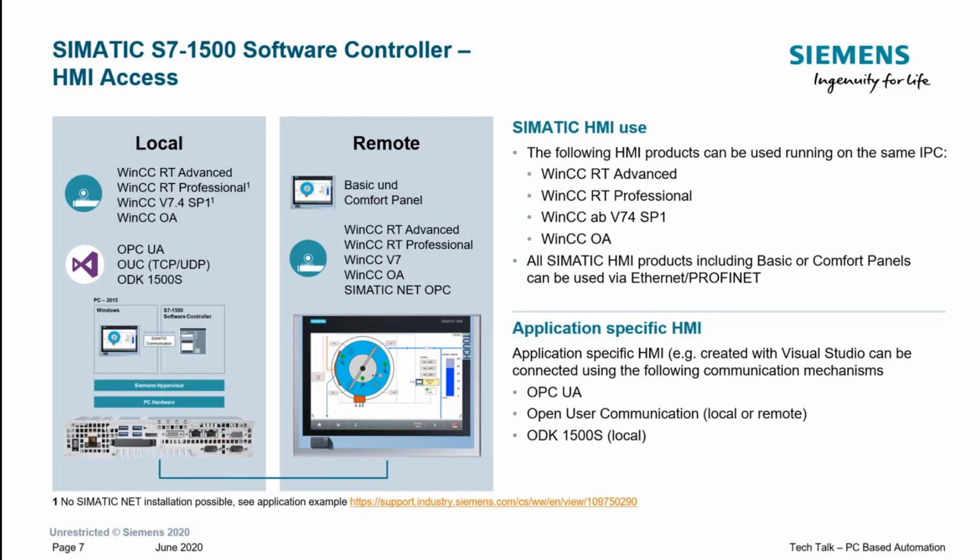Now underneath, you'll see that's actually the Visual Studio logo. So that's indicating that if you wanted to engineer or had already engineered your own operator interface in a .NET based language, the mechanisms to talk to these soft PLCs would be through OPC UA. So there's a lot of libraries for the .NET framework to make this easy. We've then got open user communications. So that obviously is covering TCP comms and UDP comms. Or we can use the ODK, which we will come on to later in this slide deck.